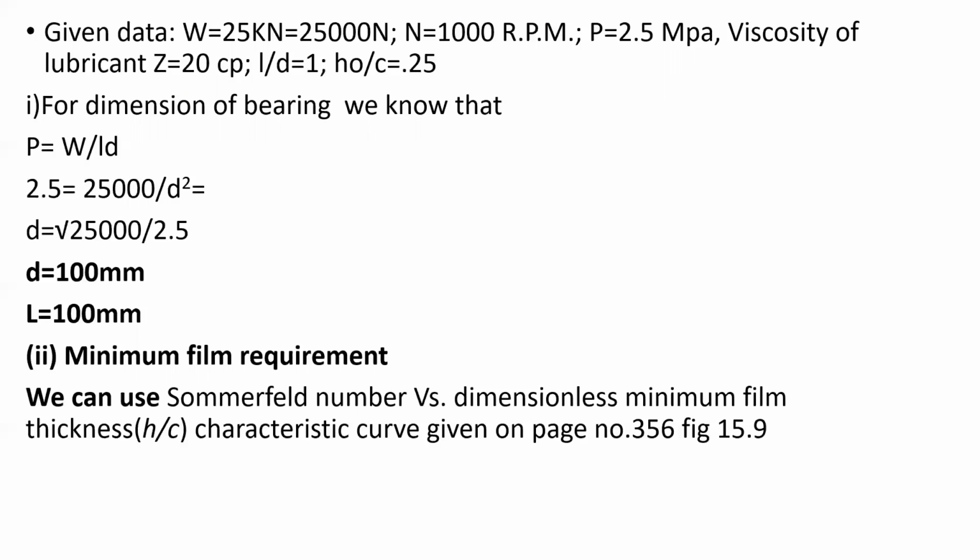But in this problem, neither the roughness of the bearing and the journal nor the machining factor is given. The machining factor means what type of machining has been done on the journal: whether the journal is polished, rough machined, well ground, whatsoever. But nothing is given in this problem.